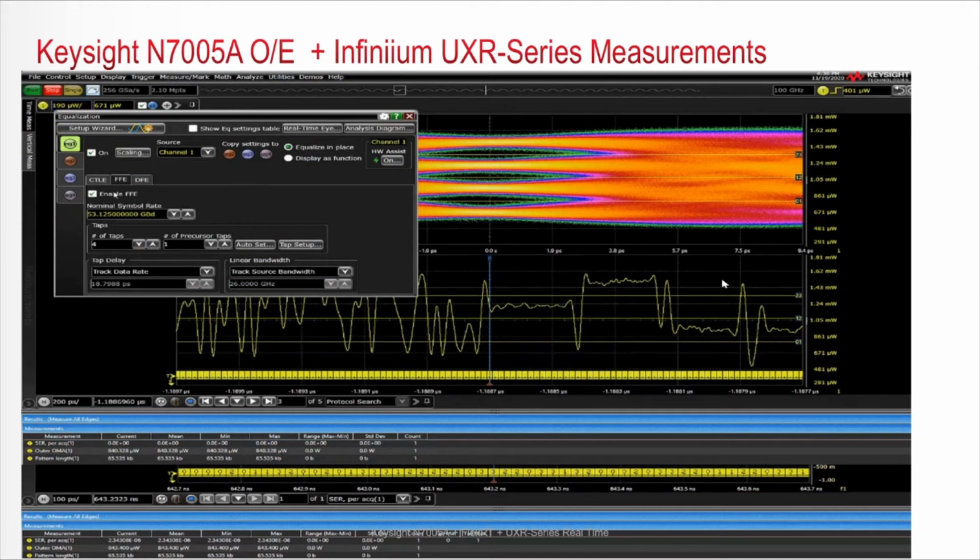The cost of too many taps comes in many forms, ranging from high power consumption concerns to real estate issues. Here we are reducing the number of feed-forward equalization taps to the point where our error rate starts to increase. We then localize the precise PAM4 symbol where the failure is occurring and make intelligent equalizer configuration choices to advance the design to work around that single point of failure.